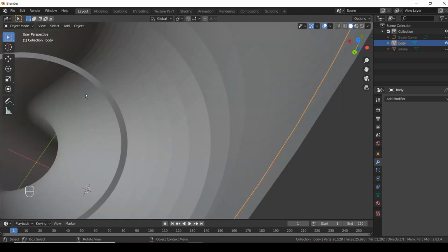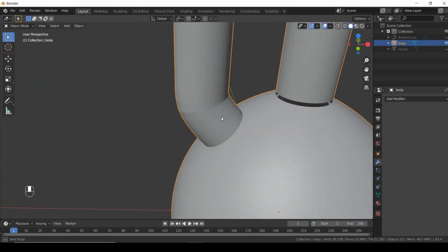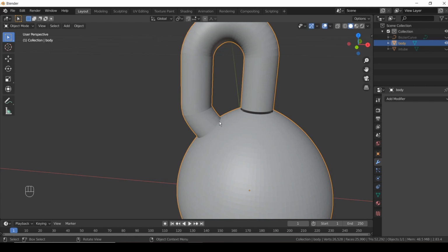Sometimes when you're chopping these together, you can get a problem where it'll leave a face and a join in here. If it does that, all you have to do is go around and delete the vertices out of the inside and the vertices from inside this gap. That's a problem with bool tools. It doesn't happen quite a lot. If you've been following along with this tutorial, it shouldn't have happened to you. Okay.